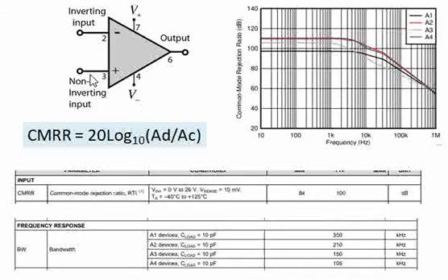Considering that we take the difference of pins 2 and 3, non-inverting minus inverting, and then multiply by gain, the noise that got induced onto these pins, as it is the same in amplitude and in phase, must get negated. That means noise must get negated.